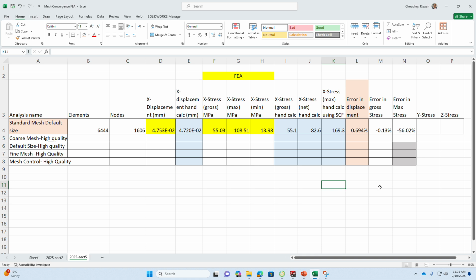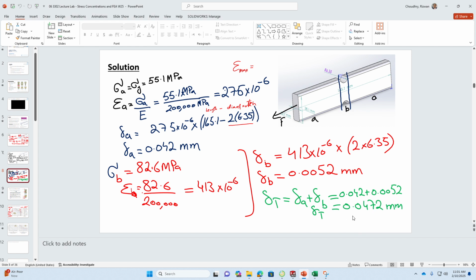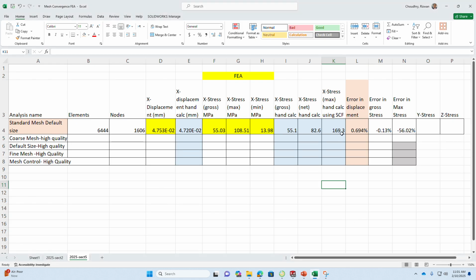If this number is also wrong, then you should reconsider, okay, because the displacement results are cumulative and they are not highly dependent on accurate calculation of stress concentration. Because if you remember in the class, we use this assumption over here, and then we calculated the total displacement, which I am comparing against. Okay, right. So since this number is okay, I can say that basically the problem is I'm not really capturing the highest stresses in the most stress concentrated zone.